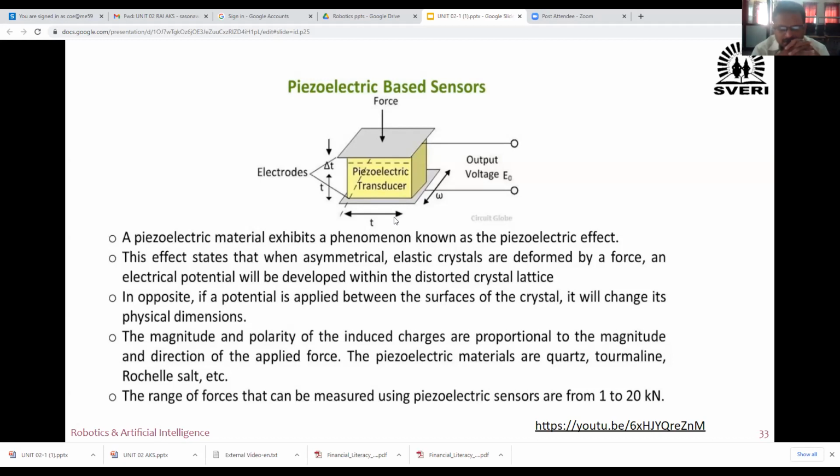That is the accelerometer. One part is there, that in that accelerometer a piezoelectric crystal is there. Therefore, whenever a machine or system is going to vibrate, if we have to measure the vibration of that system or machine or any type of beam, simply supported, cantilever beam, fixed beam or overhanging beam, we have to place that accelerometer on that object, maybe a machine or different types of beams, just as I have told you.